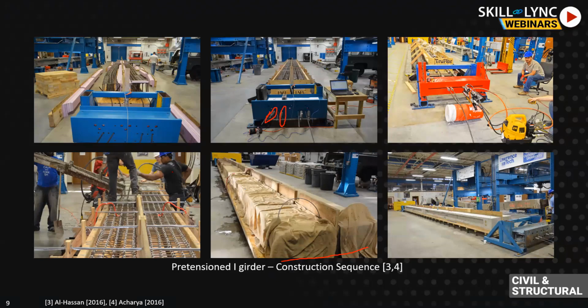So what we do when we pour concrete at this stage, we make some samples, some concrete cylinders, and then we cure them, and then we break that cylinder. Once we make sure that the concrete is okay, it has attained initial strength, then we cut it. And after we cut it, you can see we deform it.